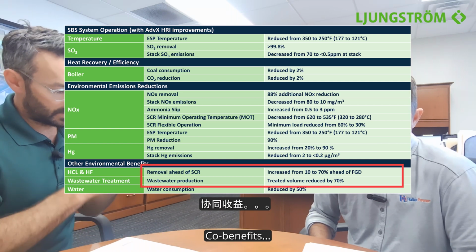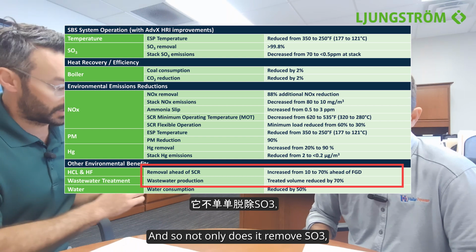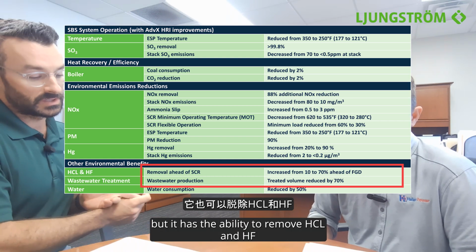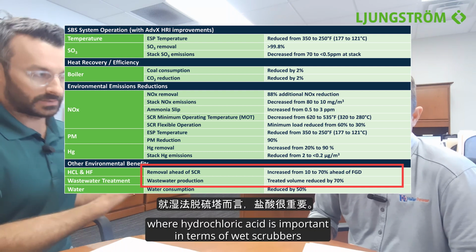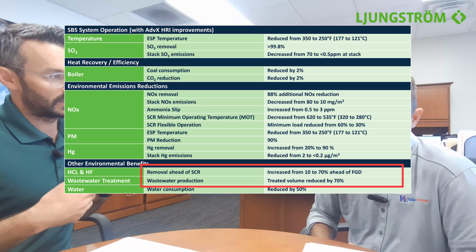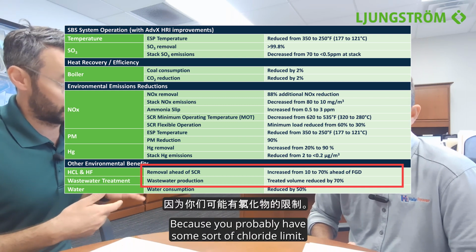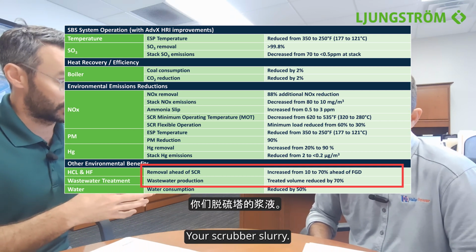Co-benefits: SBS removes acid gases. And so not only does it remove SO3, but it has the ability to remove HCl and HF. Where hydrochloric acid is important in terms of wet scrubbers is that it dictates your blowdown rate off of your scrubbers, because you probably have some sort of chloride limit in your scrubber slurry.